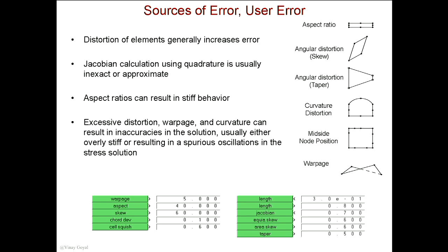Here in HyperMesh, for example, you can click any of these buttons and it will show you, okay, this set of elements, and it will highlight them for you, has a Jacobian of 0.7. Well, 0.7 is good, but if it's anything less than 0.7, it's going to highlight them for you, and you may want to revisit those elements a little bit more.